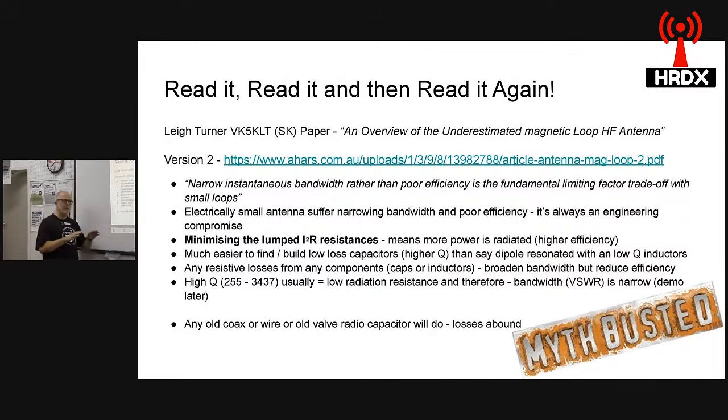And it's one of those engineering compromises all the time. And I'll demonstrate that in 2 slides' time. Electrically small antennas always suffer from being narrow bandwidth, whether they're verticals with loading coils or combinations, trapped dipoles or whatever. It's always an engineering compromise.